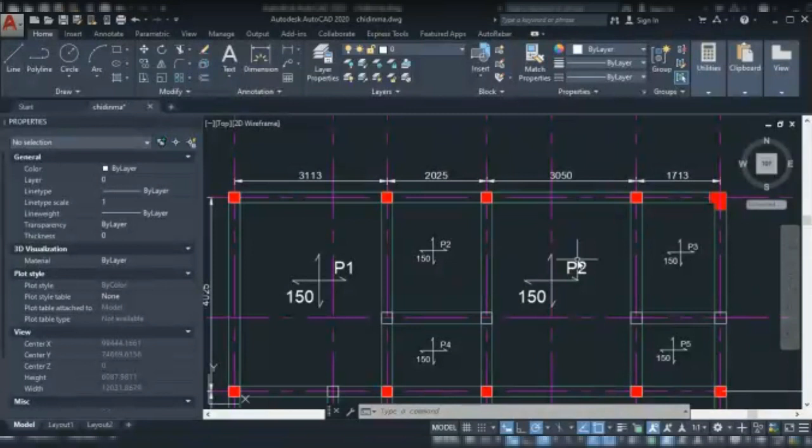So let's take 12 mm. 12 divided by 2 will be 6. So it will be 207.353 plus 6. Then your link's diameter, the minimum is 8 mm, so we are going to be using 8. So plus 8. Then your concrete cover, we'll be using 25 plus 25. So we have that to be 246.